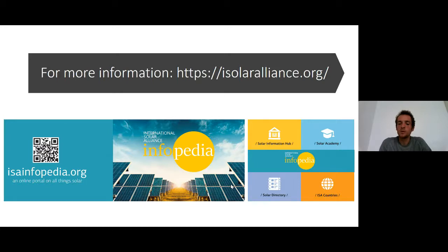So it can handle a large number of PV modules, and it generally has a very high efficiency as well. As you might know, you have different types of inverters: micro inverters, string inverters, and central inverters. Of course, for utility-scale projects, you use big inverters, so mostly central inverters, and the power is mostly around 500 kilowatts.